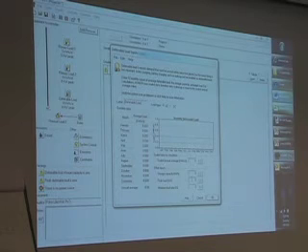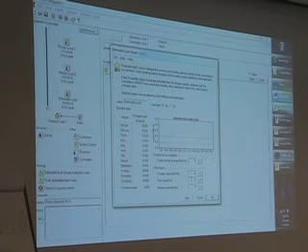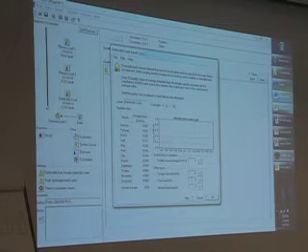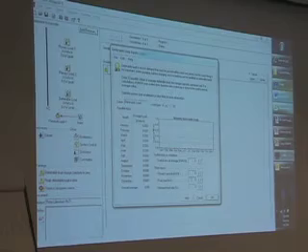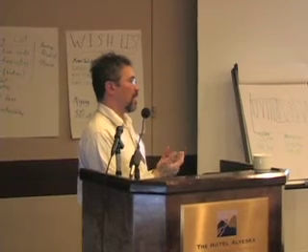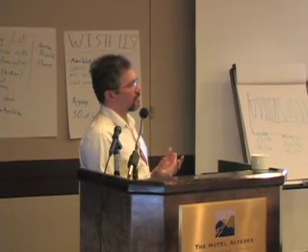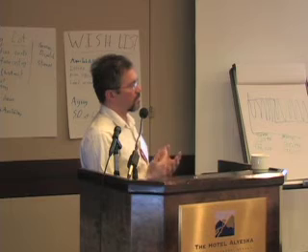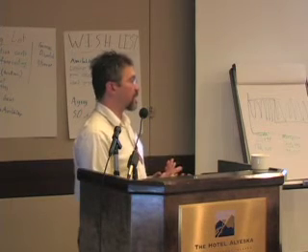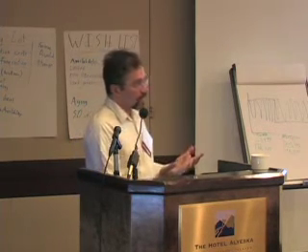But it's different than a pure dump load, in that when the tank gets empty, we need to fill it, even if it means turning on the diesel. So this is an essential load, but it's one where we have some flexibility over the timing of when you meet that load. So in a sense, it's a less expensive way to store excess renewable energy.